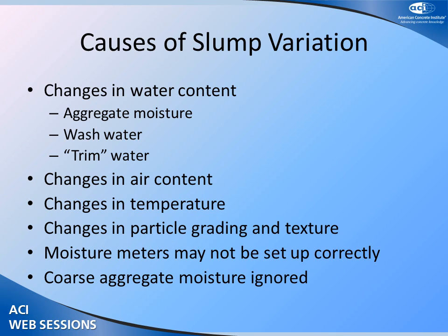And of course, hopefully all this is being accurately measured in the batching system so that when you get your batch weights on your batch ticket or you go back and look later, you can actually find out how much water was placed in that truck. Now, the other dirty little secret is sometimes there's water supplies available at the batch plant that don't go through the normal metering system. And so water can be added without showing up in the metering system. But that's why you do batch plant inspections in advance, to make sure that you understand how the water is getting into the batch system and to make sure that you're not going to have unmeasured water going into the batch system.